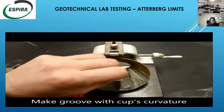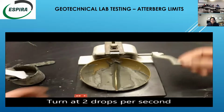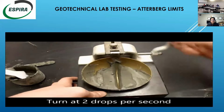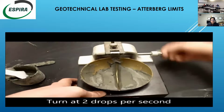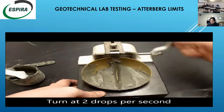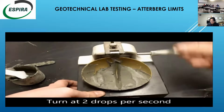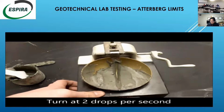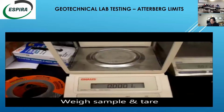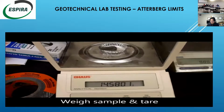The groove between the soil should close after 25 to 35 drops. If the groove closes before 25 drops, it is too wet. And if the groove closes after 35 drops, it is too dry. The water content must be changed. Once the groove closes between 25 to 35 drops, the soil is collected into the tare and massed, dried in an oven, and massed again. Finally, the water content is found at the liquid limit.